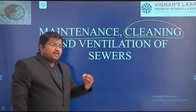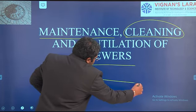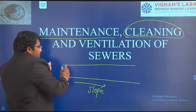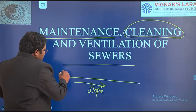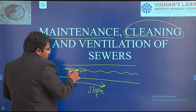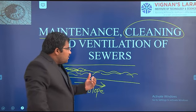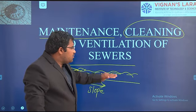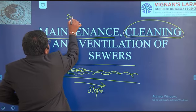Since the sewer is carrying sewage, it is laid with some slope from upstream to downstream, so the sewage will flow like this. Along with the sewage, many other materials float or move along. In the previous class we learned that the velocity of flow should not be too low and should not be too high. If it is too low, there will be a situation called silting.